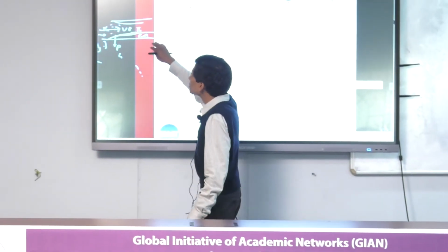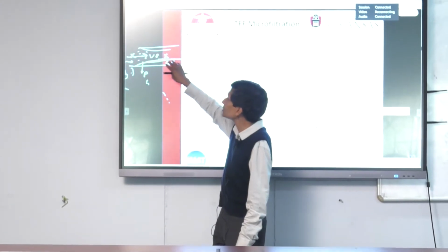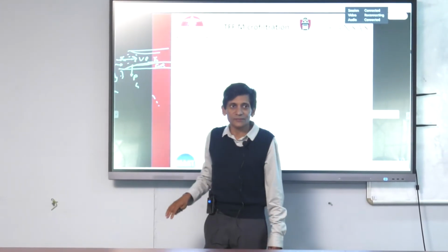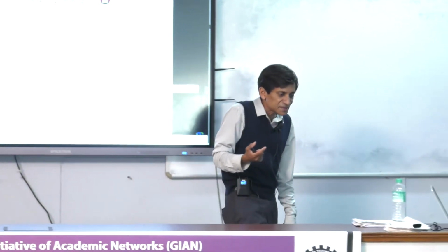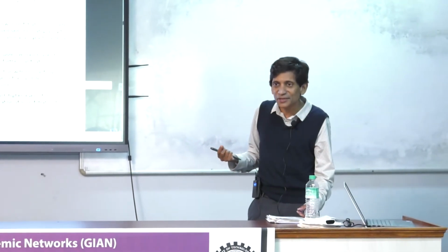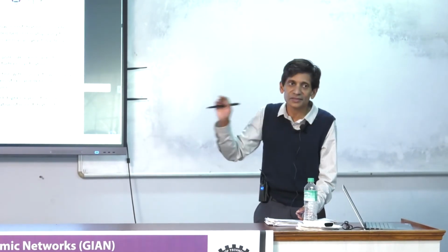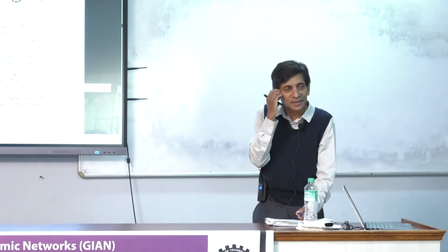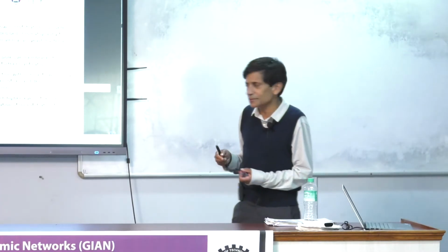The more that deposits here, the faster this starts to go through, the more the wall shear rate goes, the more it starts to suppress cake formation. So that is the whole beauty, if you like, or the idea of tangential flow microfiltration. You limit cake growth because you have this shearing on the surface. Okay, that's why this is appealing compared to dead end filtration.